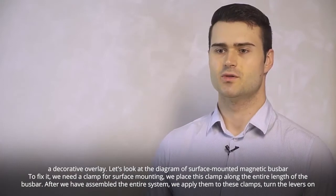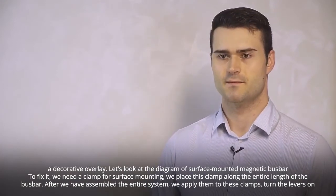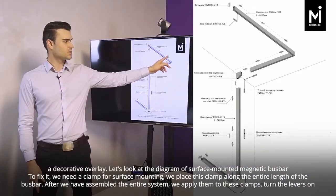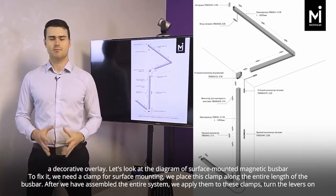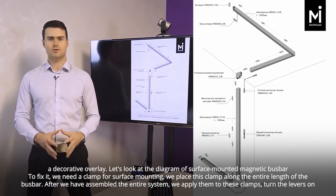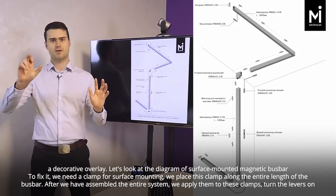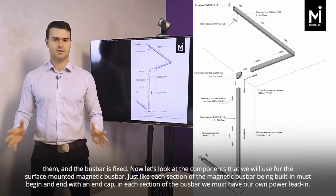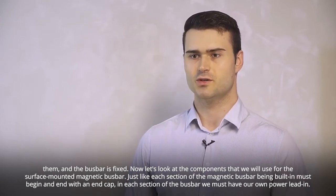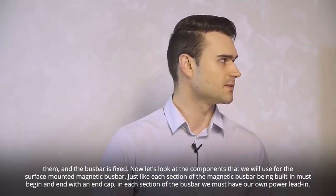Let's look at the diagram of surface-mounted magnetic busbar. To fix it, we need a clamp for surface mounting. We place this clamp along the entire length of the busbar. After we have assembled the entire system, we apply them to these clamps, turn the levers on them, and the busbar is fixed.